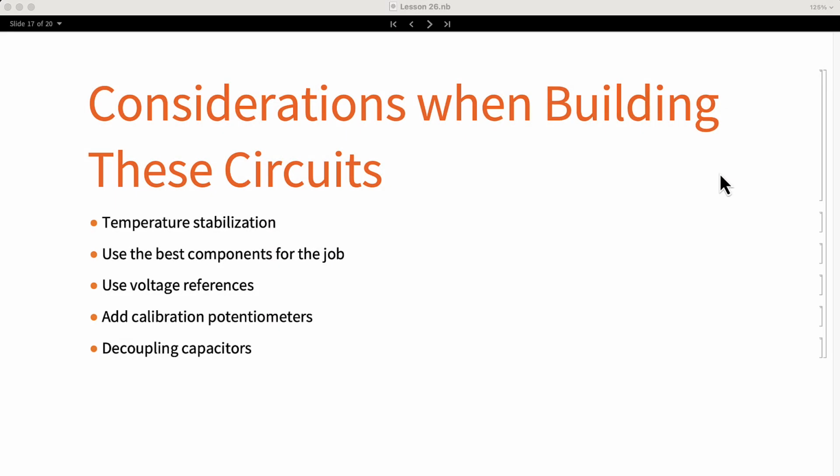As I mentioned in the beginning of the lesson, the circuits work fine, but a few things can be improved. For example, for the oscillator, I did not put much effort into adding temperature compensation. The voltage to exponential current converter needs to be carefully built using transistors with similar characteristics. In the literature, we can find how to do this improvement.